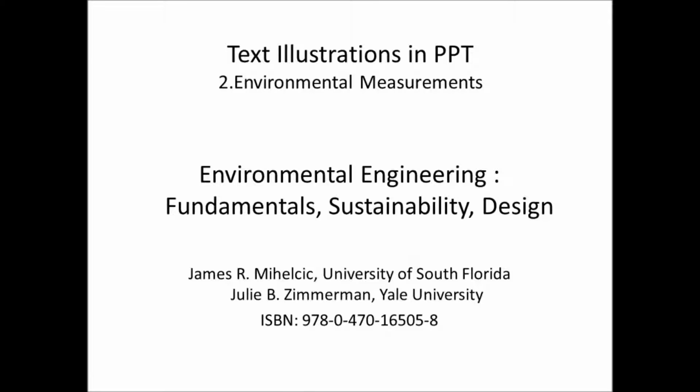2.5.1, normality. Normality is typically used to define the chemistry of water, especially in instances where acid-base and oxidation-reduction reactions are taking place. Normality is also used frequently in the laboratory during the analytical measurement of water constituents. For example, Standard Methods for the Examination of Water and Wastewater has many examples where concentrations of chemical reagents are prepared and reported in units of normality and not molarity.